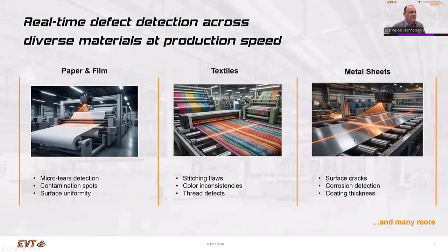And of course, for the paper, the illumination is not so difficult, so you could maybe, but not with the speed, use a 2D camera. But if we have a look at this metal, once again, it's very difficult to get a good illumination of a shiny surface because you get a lot of reflections with a 2D camera.